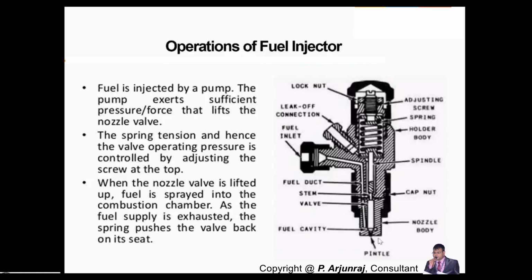Basically, it will spray and help the combustion. But when the fuel supply is exhausted and there is no fuel supply here, there is no pressure here. The spring pushes the valve back to its original location, so the nozzle valve remains on its own seat, as at the initial stage.